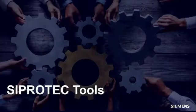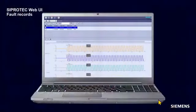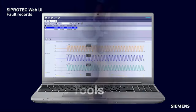And the analysis possibilities here are, of course, less than with SIGRA. SIGRA is a dedicated program to analyze fault records. Here I basically just have a time view. So I see the analog signals and also the binary signals, and I can zoom in, zoom out and scale that a little bit, but I don't have the additional editors like circle diagrams or so.